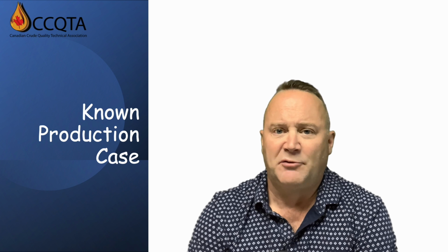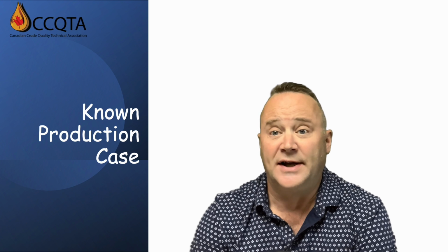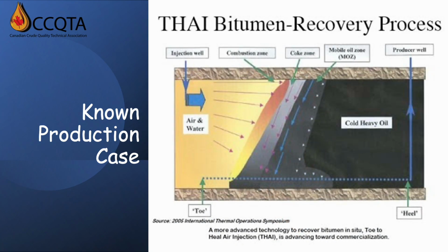Finally, while there's been limited reported evidence of organic chloride formation linked to crude production techniques, there is one known case. In 2017, the CCQTA reported on the formation of a chlorinated benzene compound in a facility using toe-to-heel air injection, or the THAI process, for oil production. This process injects air into the reservoir to allow ignition of the oil at the toe, which in turn warms the reservoir, reducing the bitumen viscosity so that it can be produced at the heel. This organic chloride formation case is believed to be due to the unusually aggressive combustion conditions involved in the process and remains the only reported case of organic chloride formation during production.